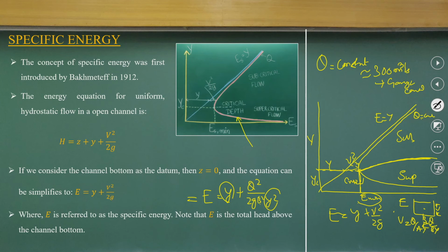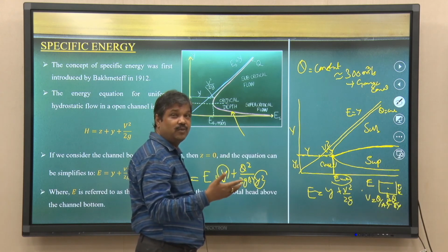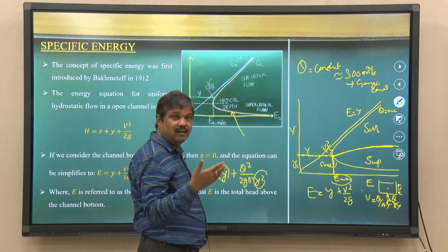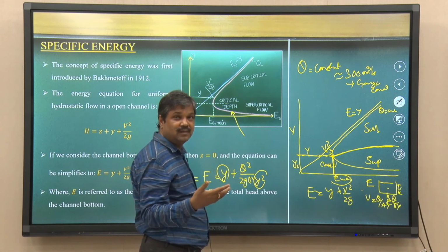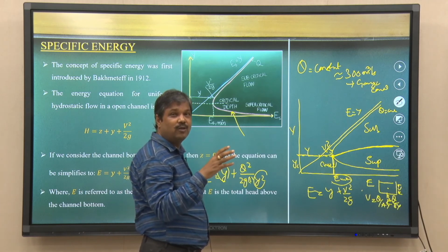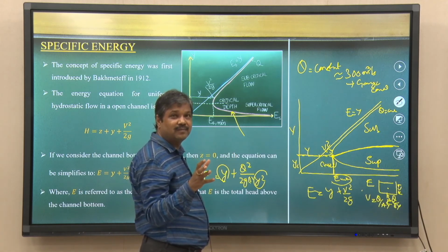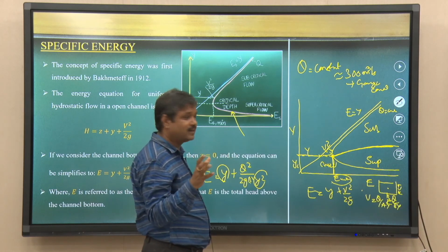That is the equation when you have the flow Froude number equal to 1, inertia force is equal to the gravity force. The second definition, which we derived, is that the velocity of the flow is equal to the speed of the surface wave. At that location, if I throw a stone, the waves created will not move in any direction.